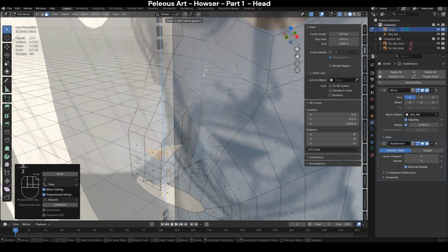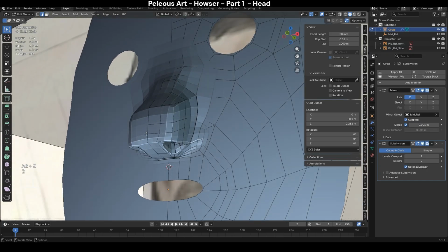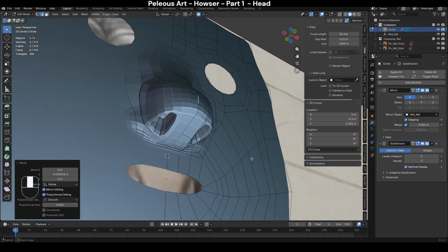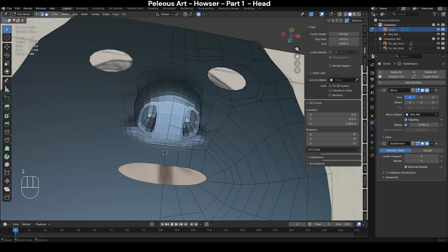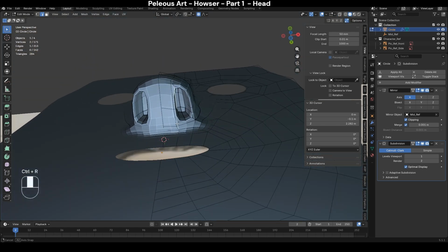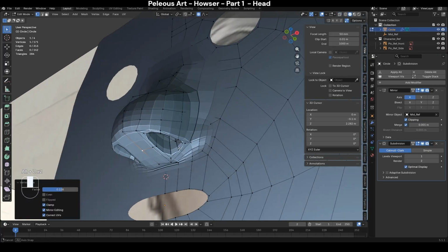Okay, turn off proportional editing, SZ0. Let's bring it back. You can do it with O, by the way. If you click O for proportional editing, let's move it on the Y gently. If you click Shift, it allows you to control the strength of the tool. If you want to do things very carefully, let's select that edge, move it a bit, move the vertex down, that as well.